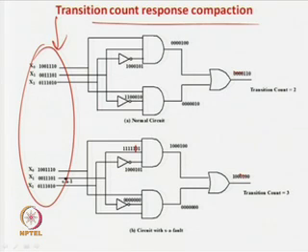If you have an exhaustive test pattern generation, like if you are using a characteristic primitive polynomial, then it is fine. But sometimes we may not be using a primitive polynomial because we may want a much smaller LFSR area, or you may not want the full pattern generation because that may lead to much more area. Then you can use another LFSR without the primitive polynomial. So you do not go for exhaustive pattern generation, but you can have whatever number of patterns is required.